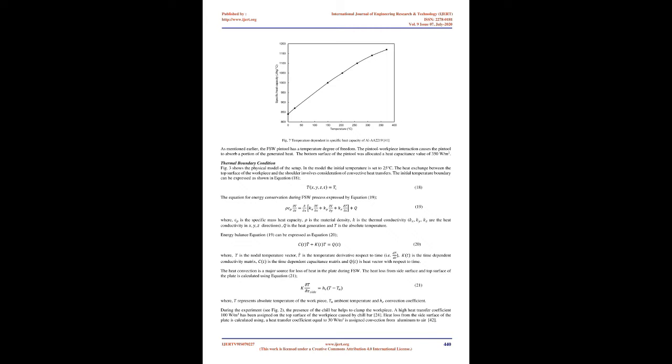The original plate length and width have been truncated, but the actual thickness was maintained in order to reduce simulation time. This enables the simulation to capture the behavior of the steady-state portion of the FSW process successfully without the need to simulate the entire steady-state region.